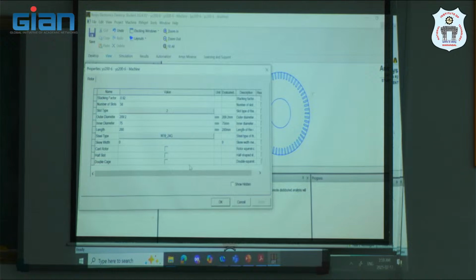In the student version, there is a bug. If you go into the rotor window and click on the material type of the steel, the software will crash. So don't do that. It's just a bug in the student version of this 2024 release. The latest is the 2024 release, and just in the 2024 release they have this bug. When they release the next version, they will fix it. The reason I'm saying that is that otherwise people have built it from scratch.